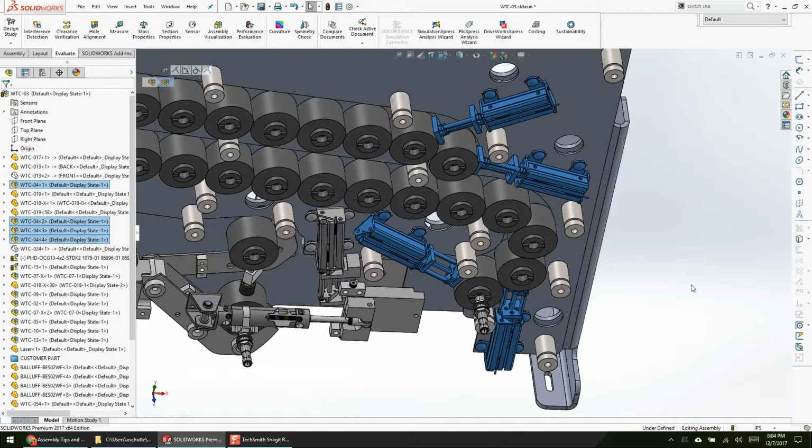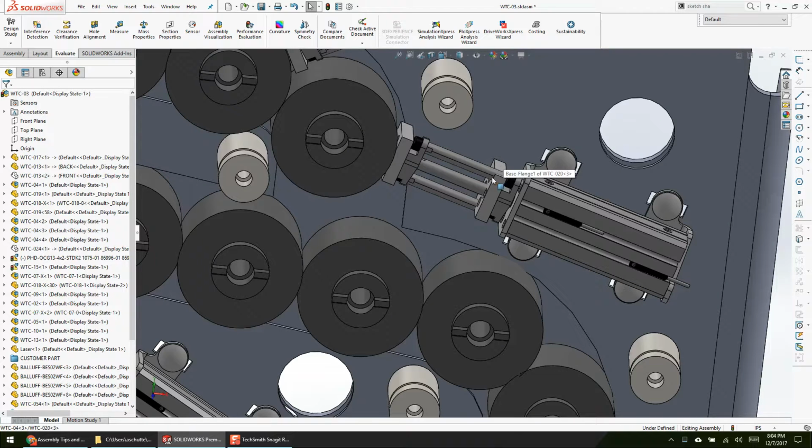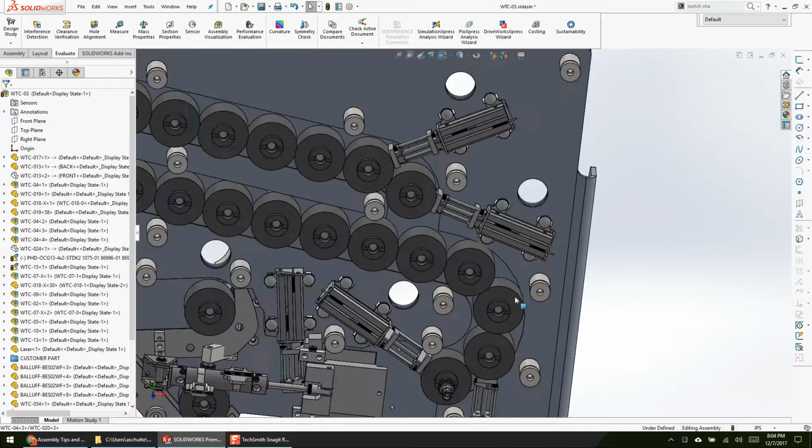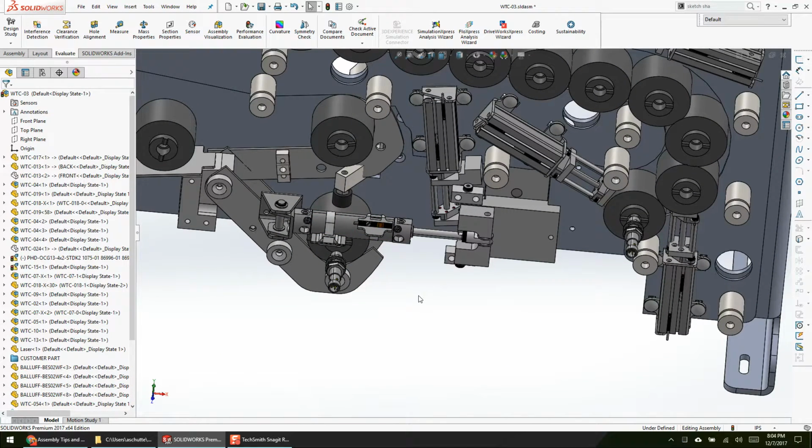If I was going to do it, what I would do is the exact same thing, and then before I was ready to release it for manufacturing, I would go through and clean everything up after I've proven the design. There's a lot of things I'll put in or not put in. Once the design is proven, like fillets. Fillets should always be at the very bottom of your feature tree. Unless there's a compelling reason otherwise, fillets are at the bottom. Lots of reasons why, but predominantly because fillets are performance killers, largely aesthetic, and only necessary 3 seconds before you